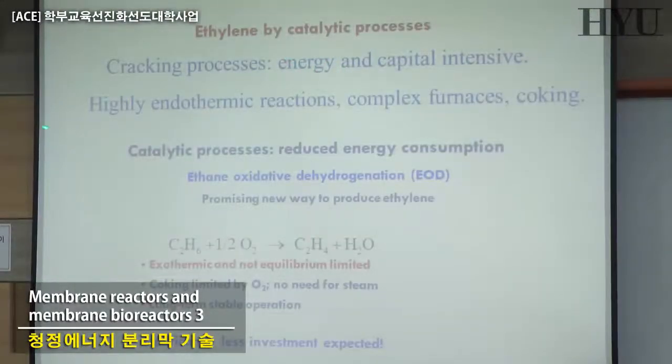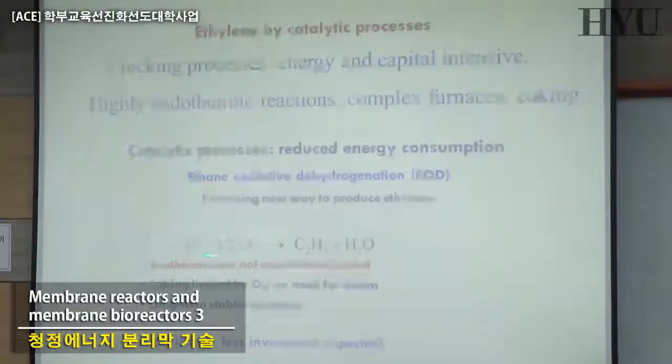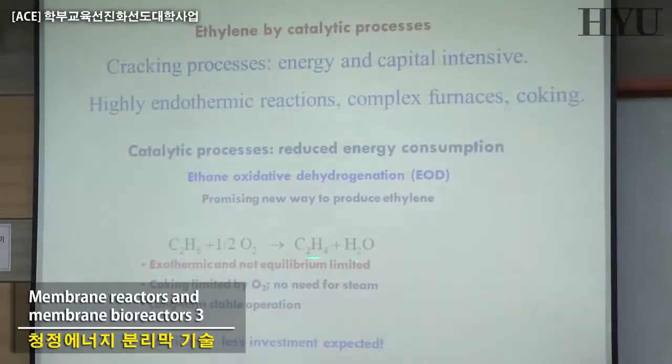Instead of cracking, you can have a catalytic process at much lower energy consumption, and that is ethane oxidative dehydrogenation. And how can that be done? The reaction we are considering is exothermic and not equilibrium limited. There is no need for steam. It is long-term stable, coking is limited just by oxygen, and there is much less investment.